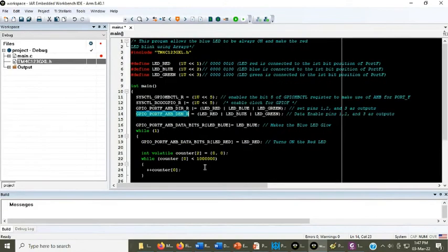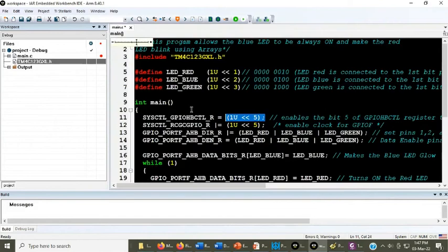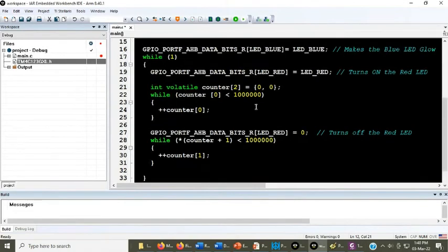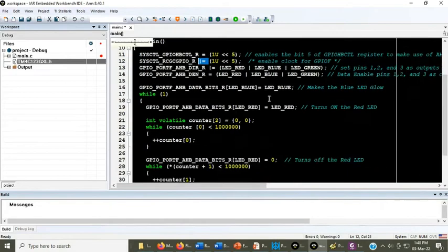This is working. Okay, you can take the help of the header file, go to the particular register, and enter the value using bit level shifting. Done. And you can use bitwise ANDing and ORing. This is bitwise ORing to make a particular bit high. Bitwise ANDing will be used when we want to make a particular bit 0. Okay, here we have not used bitwise ANDing till this part. Okay, done.